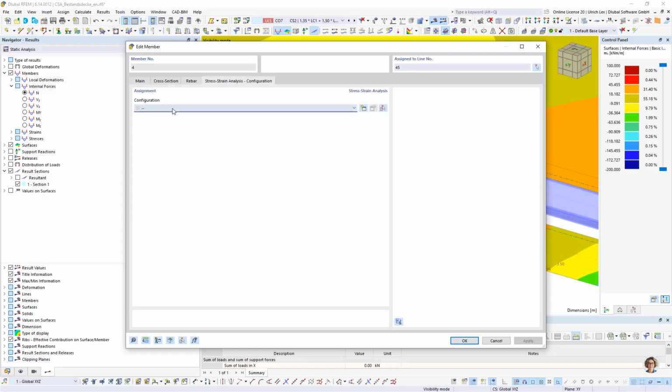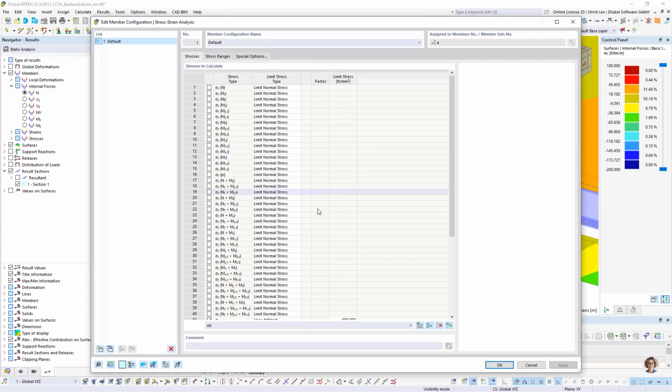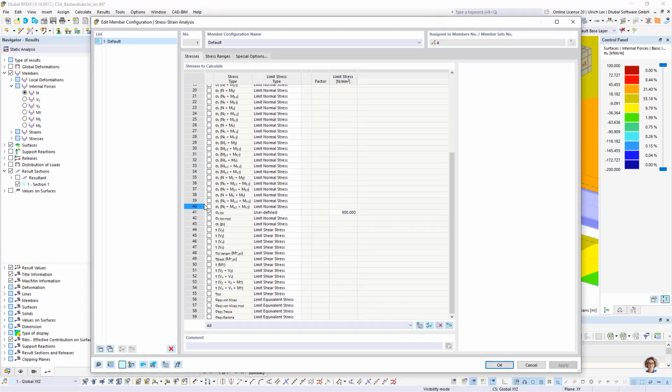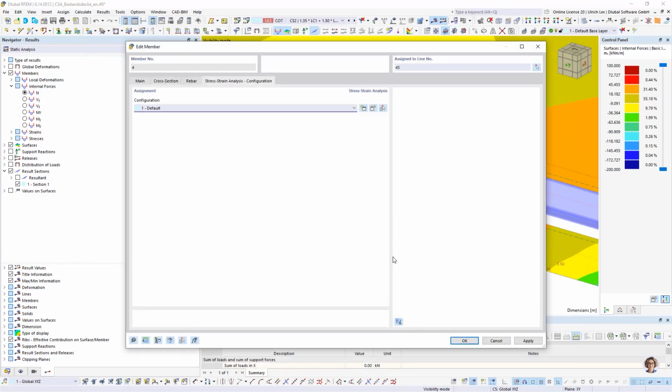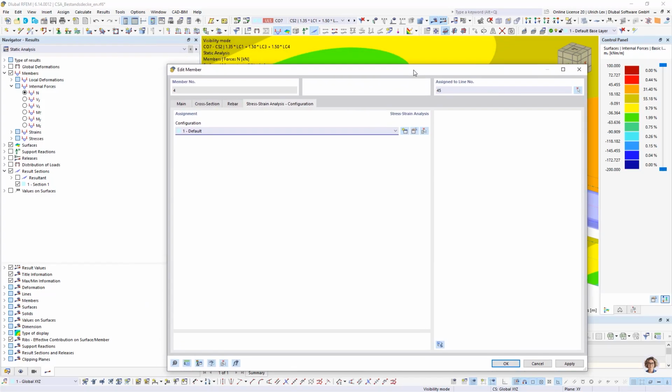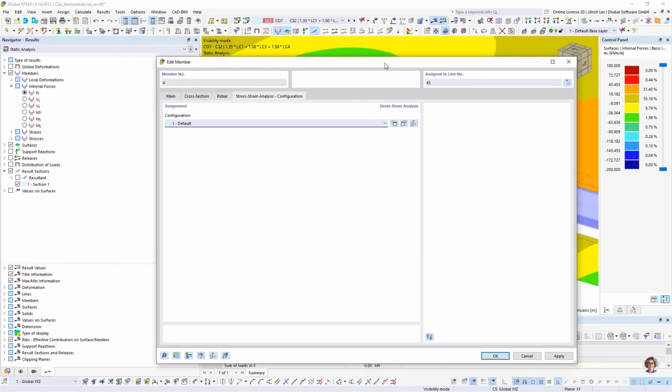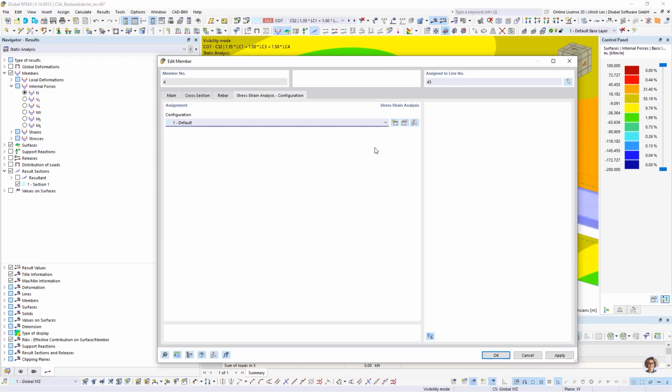You can add here a stress-strain analysis, and choose maybe the sigma in X direction to check it against a limit stress, and run it in this way and design. But it's only a stress-strain analysis. Maybe you need some additional checks for it.